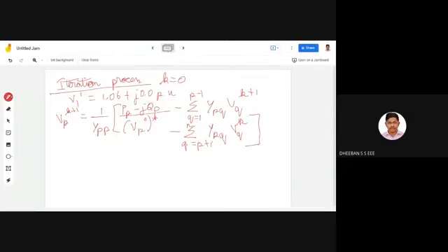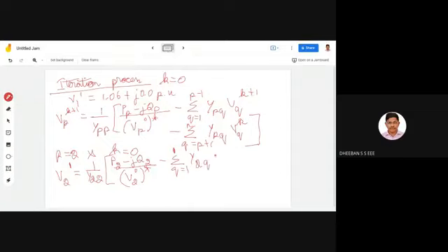So now coming to the value of p equal to 2 and k equal to 0 in this voltage equation, if you put it in, V2^(1) will be equal to 1 by y22 into (P2 - jQ2) divided by V2^0 conjugate, minus summation, so q is equal to 1 and p is 2, so 2 minus 1 will again be 1, so y2q followed by Vq, where the k value is 0.